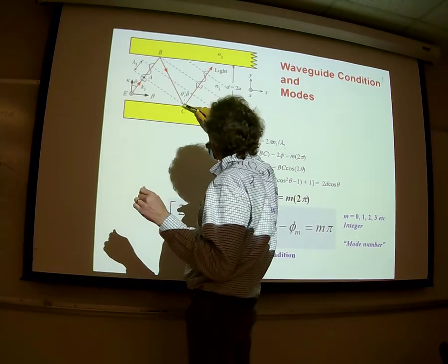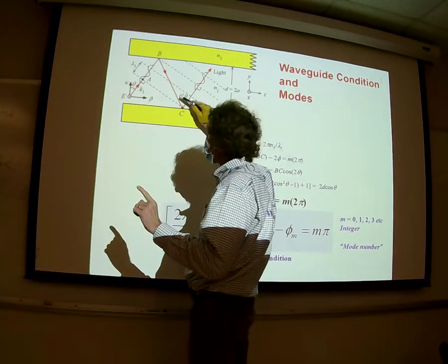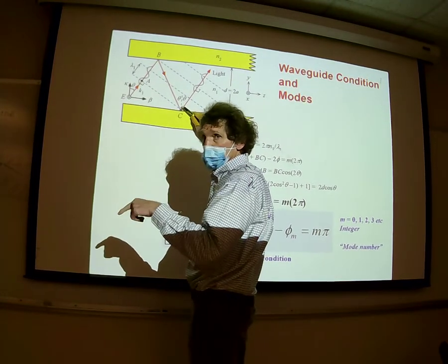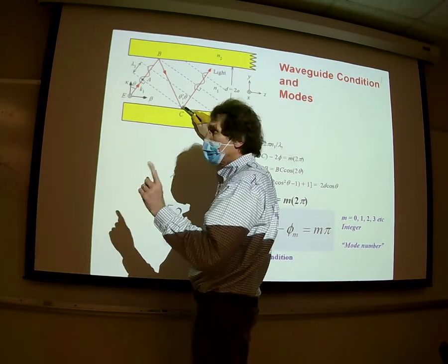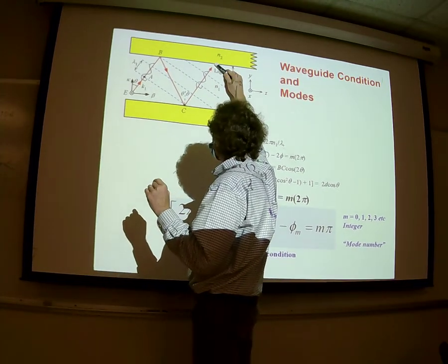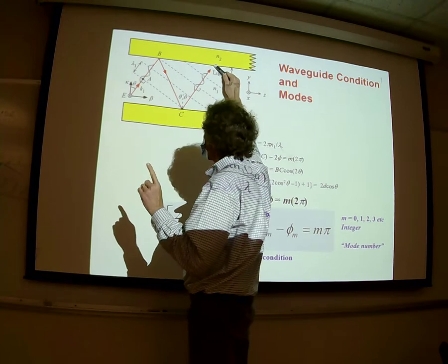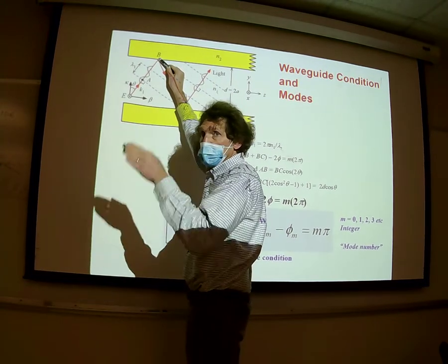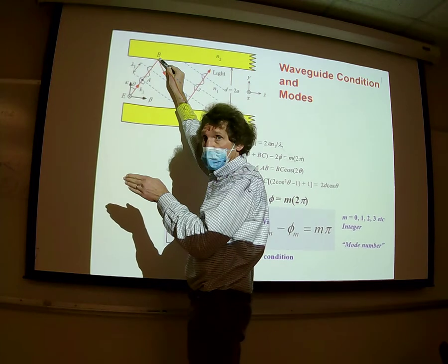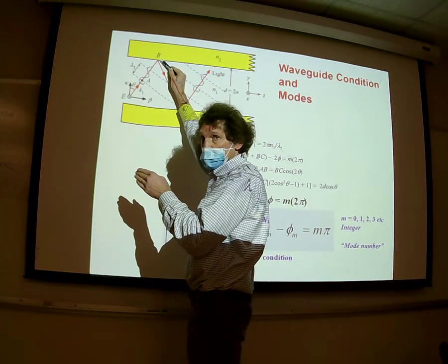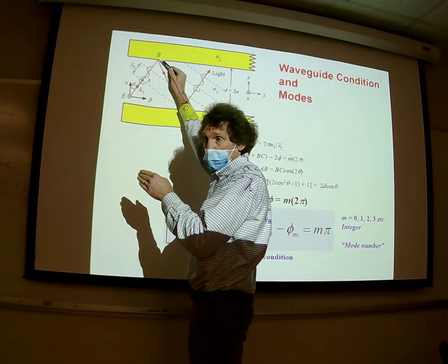Going to hit here. There's a reflection coefficient first along this path length right there, the phase change, right? Then it hits here, it hits a reflection coefficient, then another phase change, comes back here. But when it strikes here, it has to have the same phase as it struck here, call it A, in order to have constructive interference. Do you all follow me? As it gets further and further away from that, there's destructive interference. You follow me? And that wave will not propagate.